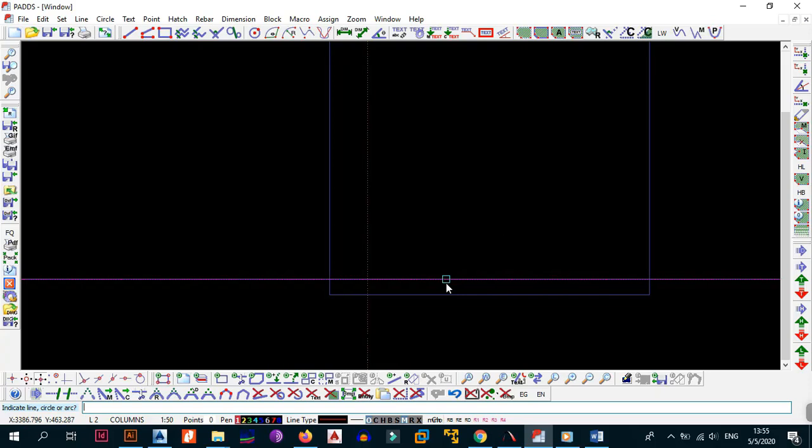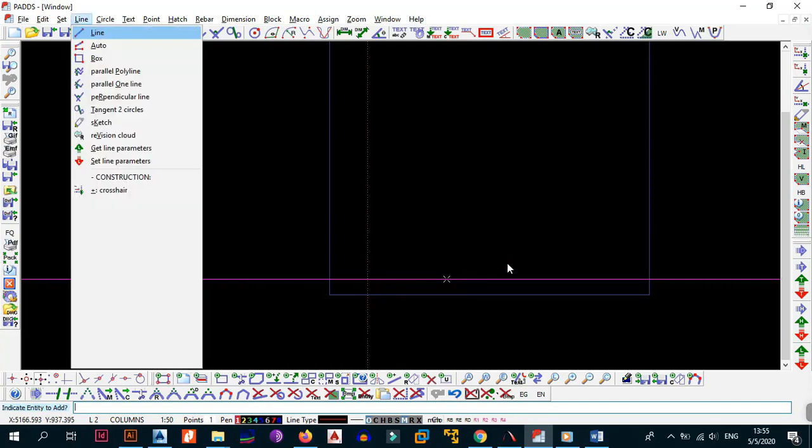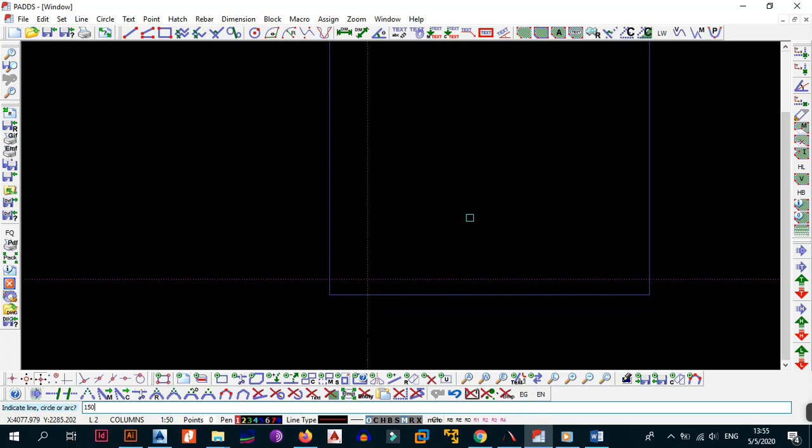So the first thing is this first line that we established, the LX. Let me just select it, which is BA. This will represent the top of your base. So from the top of your base, you remember we need to go by 1,500. Okay, let's LP 1,500. Right, this is this portion.